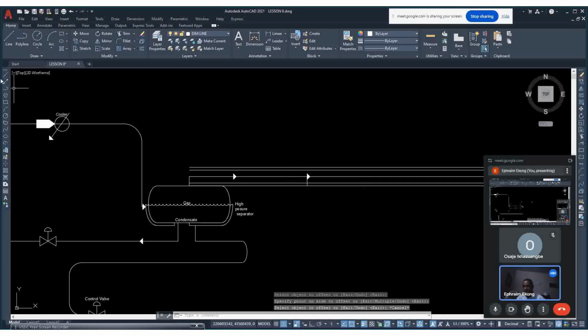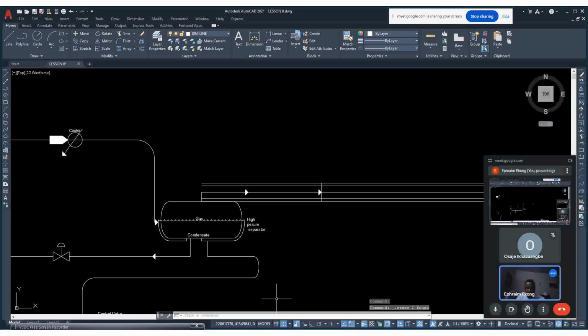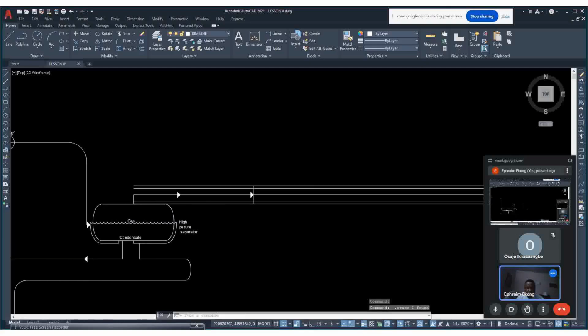Okay. So what next? You go to line. Click on line. Ensure your auto is on. Click on offset. Click on extend and press enter. So you extend it down to this point. Here. Now to what distance from here to here? We say 1,000. Offset 1,000. Let's offset 1,000. Offset and type 1,000. Enter.